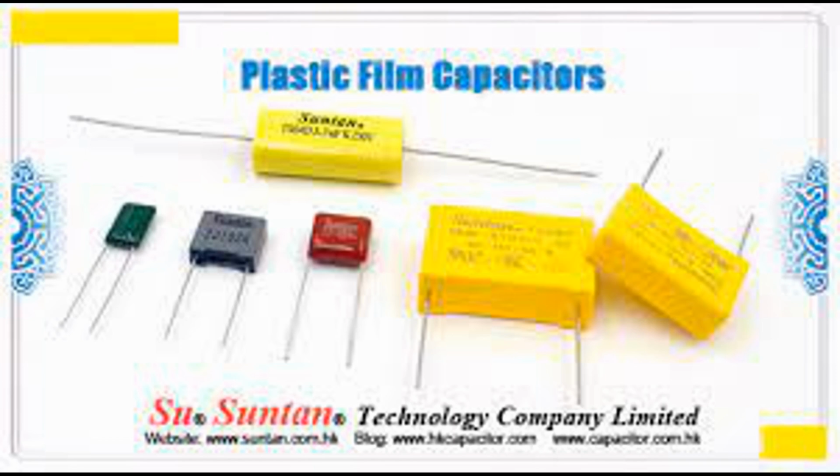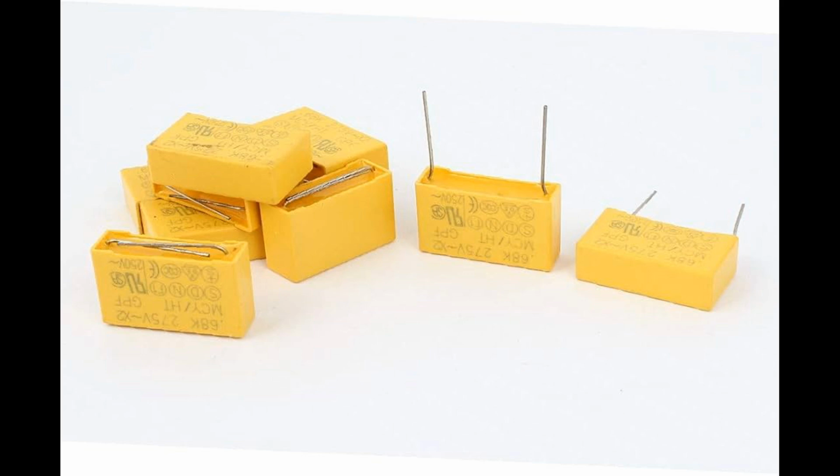4. High insulation resistance. Film capacitors have high insulation resistance, which reduces leakage current to a very low level. This is critical for applications that require efficient energy storage and low losses, such as timing circuits and energy storage systems. 5. Wide voltage range. Film capacitors can handle a wide range of voltages, from low voltages in signal processing circuits to high voltages in power systems, up to several thousand volts. This makes them suitable for a broad spectrum of applications, including AC motors, power factor correction, and high-voltage power supplies.